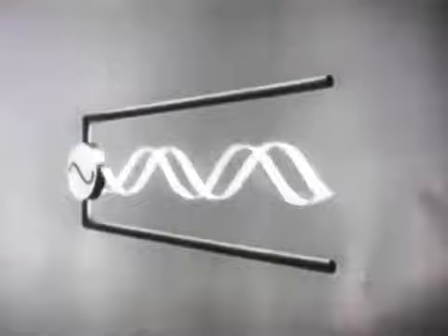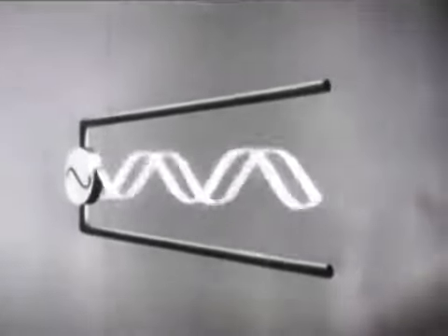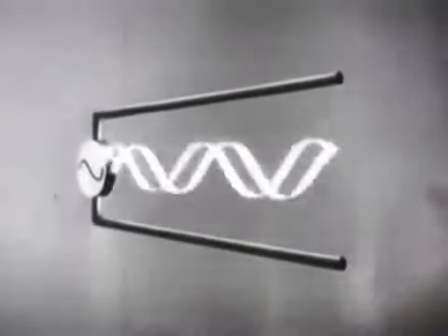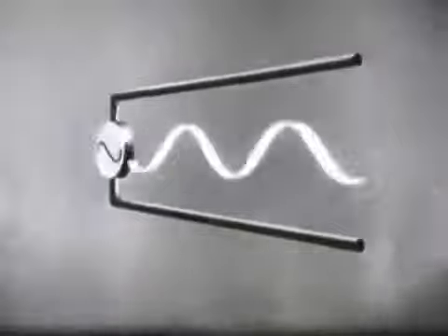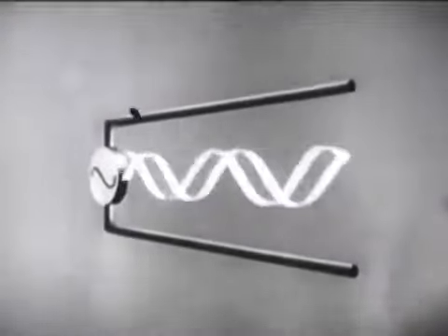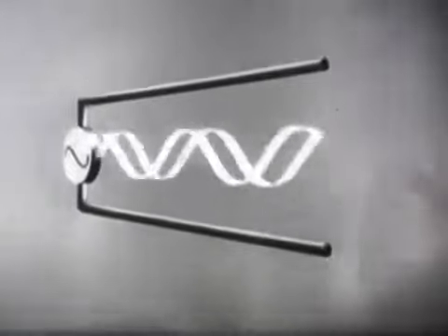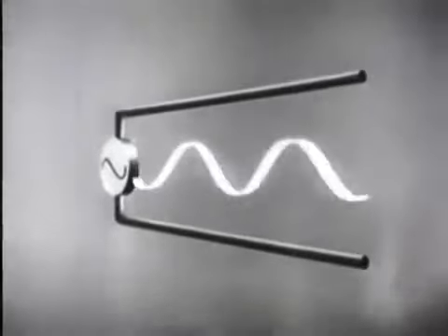An open-ended line achieves the same result. The open ends of the circuit offer maximum resistance to the passage of current. There is no power dissipation. The incident wave simply bounces back at the end of the line to become a reflected wave of maximum amplitude.